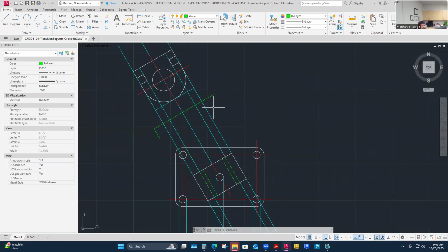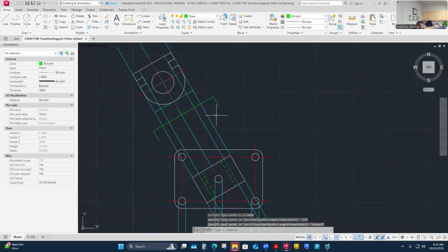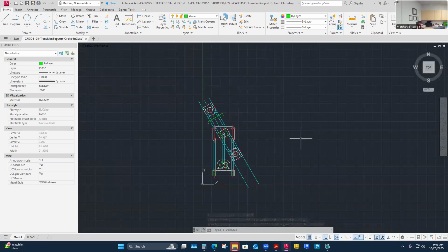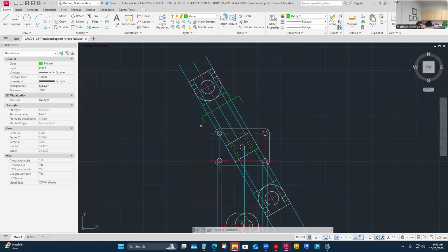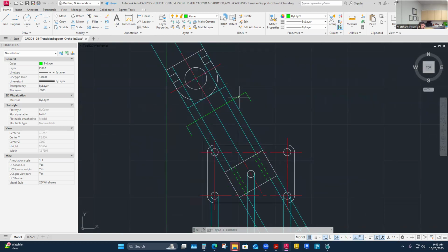All I'm looking to do is just put an arrow on the end of it. So it's not super critical, but I couldn't find that ASME had an exact standard for this. In some drawings where it was really big, a half-inch might not be sufficiently long. Maybe it needs to be an inch long. So the size of your part may dictate how long that needs to look to turn back to an arrow is what I've kind of thought as I've done a little bit of research and haven't found anything.